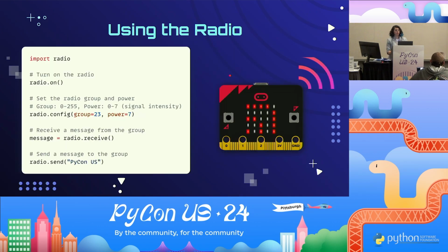So now we are going to be using the radio. The microbit has an antenna that you can use to communicate with other microbits, and it works in groups. Kind of like we have Wi-Fi channels, it works the same way, and it uses the same frequency as 2.4 gigahertz Wi-Fi. It's a specific protocol for communicating, but it uses the same frequency. And you can pass here the group. You can configure the group by passing a number between 0 and 255.